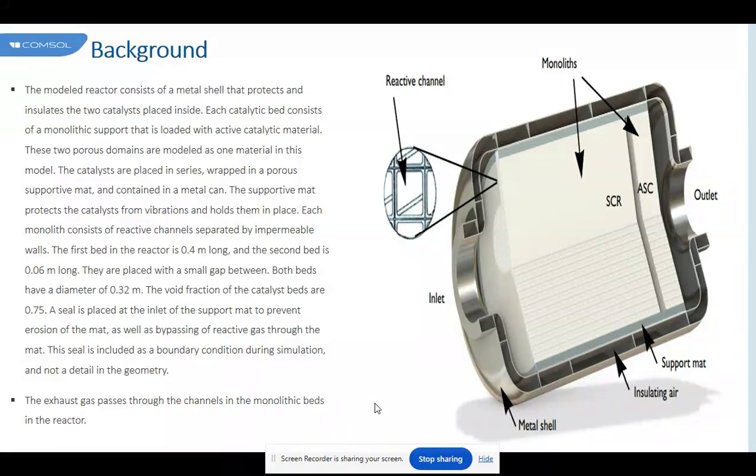The aforementioned result can be considered a negative one since what is desired is a higher conversion efficiency. Nevertheless, it shows that unbounded efficiencies are possible when combining cell densities. Positive results are also observed. We remark specifically on the case when the core and ring have the same volume. The two combinations 900 C per 400 R and 400 C per 900 R lead to the same pressure drop, but in the latter combination the CO depletion is 50% higher.